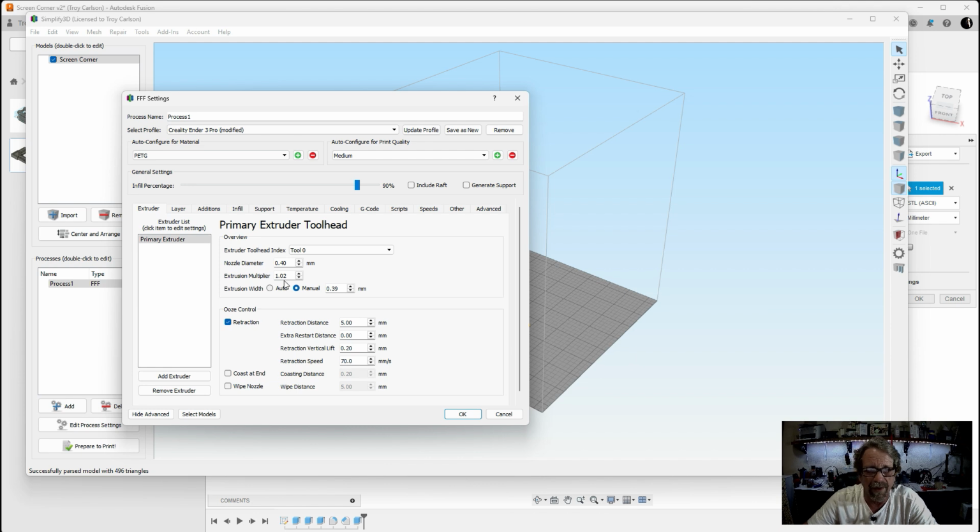Auto, at 1.02, would extrude probably 0.42 to 0.44 as far as the width, because you get smash. It's coming out, but then when it hits, it smashes outward. Those come over and touch the next one and the next one and the next one. I don't want to do that. I actually am making it less and extruding right into the path of the one before it. In my opinion, in testing I've done, it makes it a whole lot stronger.